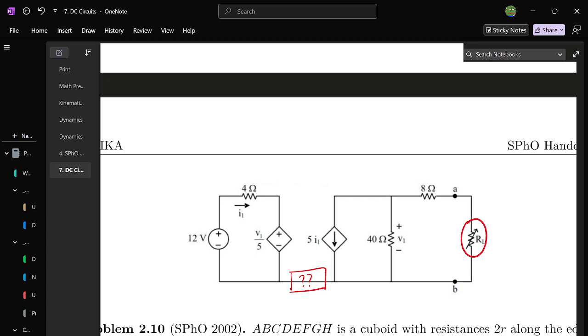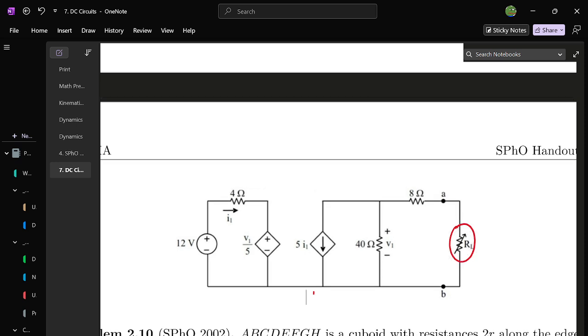Well, the thing is that you actually can do that, because in a wire that joins two circuits like that, this wire here is not part of any big loop. So it's not part of a closed loop, right? If you try to draw as many loops as you can, just experiment by yourself, you'll realize that any loop that you draw containing this wire will never be a closed loop. And because current only flows in closed loops, this means that no current flows through here. No current can even flow through here because it can never form a closed loop.